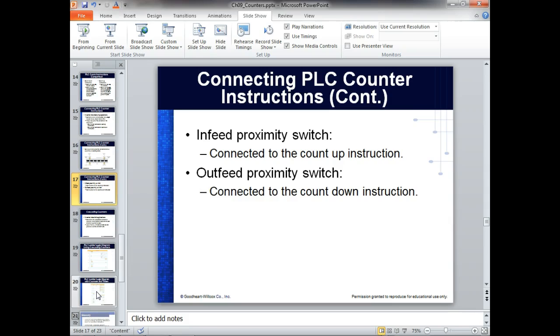So over time, the term proximity means these are solid state non-contact sensors. What do we mean by non-contact? They don't have to touch what they're measuring. So we have all types of non-contact proximity sensors that we use as counters. And we could have shown y'all some of those on the manufacturing line over there the other day. I should have shown y'all those that we could use as counters. Through the beam, what we call diffuse, retroreflective, we could use any of those as counters.